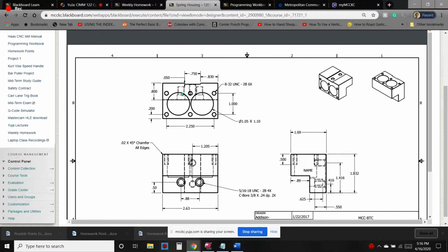So now it's time to break out our end mill and circular interpolate these holes and mill around the entire outside. And I really like milling around the outside of the whole part, because that way you know that as long as your program's right, your holes and everything are going to be centered within the contour just perfectly.